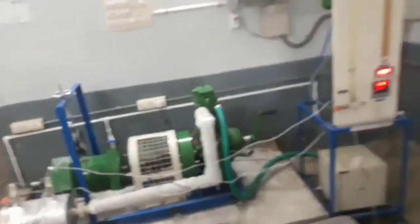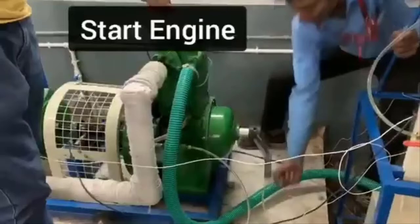Now here you can mark the initial diesel level, because we are measuring 10 ml of the diesel. Whenever the diesel stops inside the burette, make one mark, which is our starting point, and after 10 ml make a second mark, which will be our ending point. So we will mark 2 points, one at the initial level and the second at the final level. This is how we will do our experiment. So now let's do the experiment and take the readings.